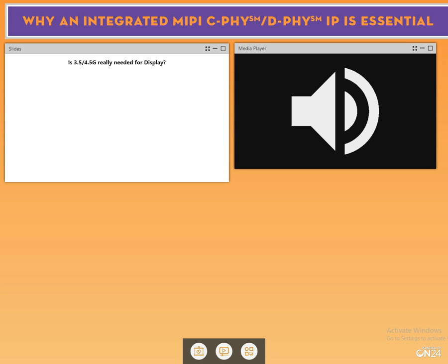In the meantime, C-PHY is the path to increase the bit rate, because for a given signal rate, we can actually achieve 2.28x in terms of bit rate. And on top of that, compression, the VESA DSC with visually lossless compression, is another option to reduce the bandwidth requirements when targeting high resolutions effectively.